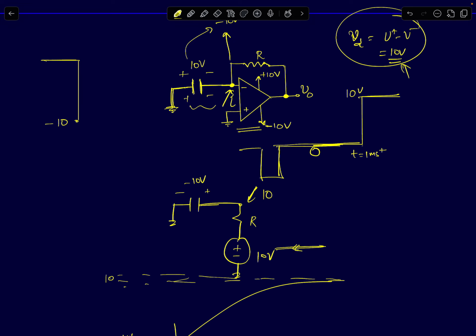So now you have a circuit like this. The only components that are active are a resistor, a capacitor, and the output of the op-amp. The output of the op-amp is at 10 volts, at one end of the resistor. The capacitor, I've shown the direction this way, is charged to plus 10 volts, and the other end of the resistor, the node voltage Vx, is at minus 10 volts. So this node voltage is at minus 10 volts right now.